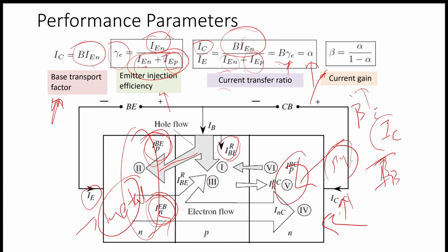So there are several combinations that we can see from the equations that we have covered in the PN junction. One is the PN junction and another is the Schottky barrier. In the Schottky barrier, we have calculated the current between the metal and the semiconductor through thermionic emission. That can be applied here. How much is the reverse current, how much is the forward current, we can apply here and easily calculate.